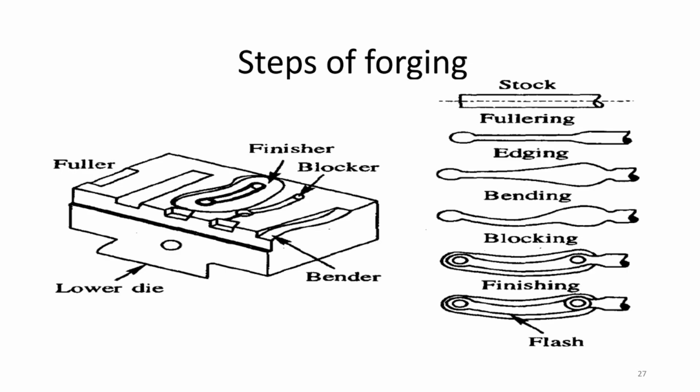Solid shrinkage will be dealt with by using the pattern allowance, but there is a middle one called solidification shrinkage, isn't it? See, firstly, your density will change for liquid and solid, right? In water it expands, but in metals, what happens?